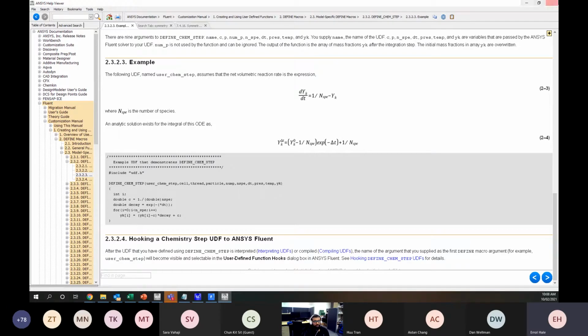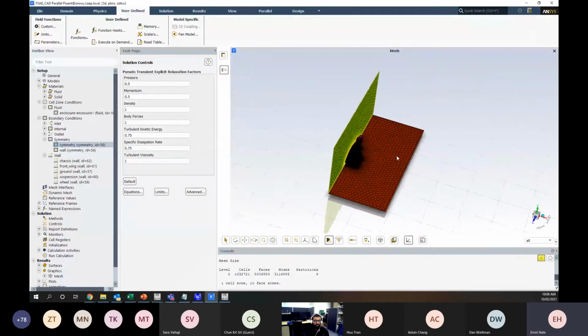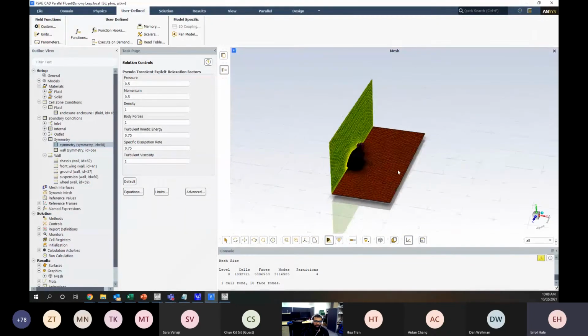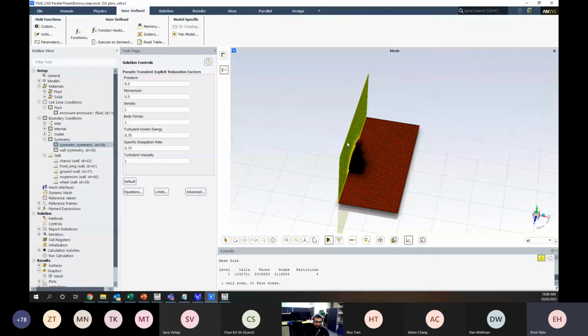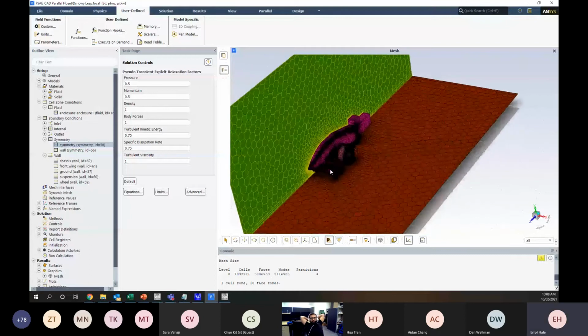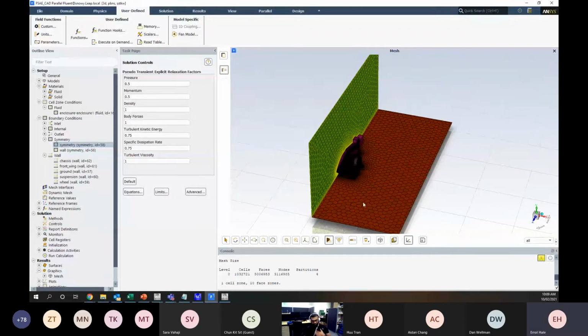How to simulate flow of a vehicle in a corner. Really interesting question, quite a difficult question as well. A couple of ways we can do it, depending on how simple or high fidelity you want to go. Obviously, we can't have a symmetry plane anymore because the flow is no longer symmetrical when it's coming from an angle. The simplest way is to just have a box domain and have an inlet, and just have some angle of the flow. And you have an outlet. And you'll turn the wheel, maybe you'll put some roll and pitch on it, depending on what vehicle dynamics you're expecting to experience in a corner like that.